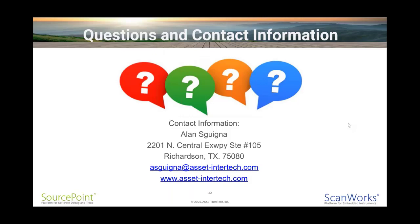Absolutely. Well, there are several different ways you can do it. When I ran that macro command via the command line, I did an output of the AX register, for example. So every time we hit the port 80 breakpoint, which was inherent in the go till 80 part of the command, we popped out the value of AX, which is essentially the port 80 contents.